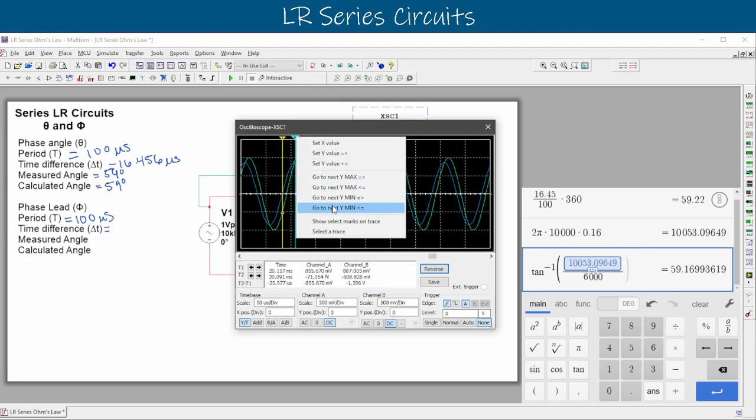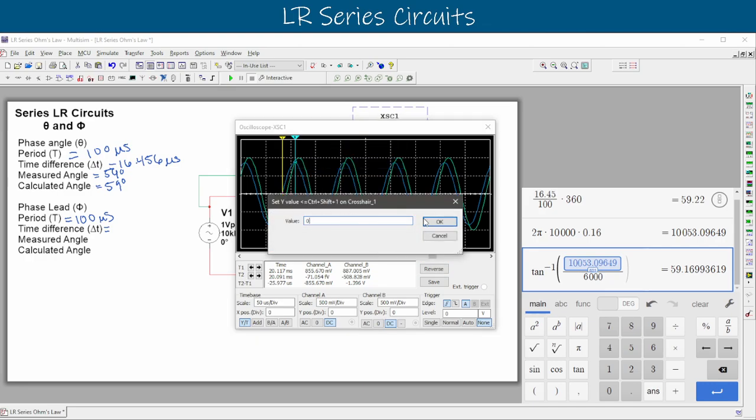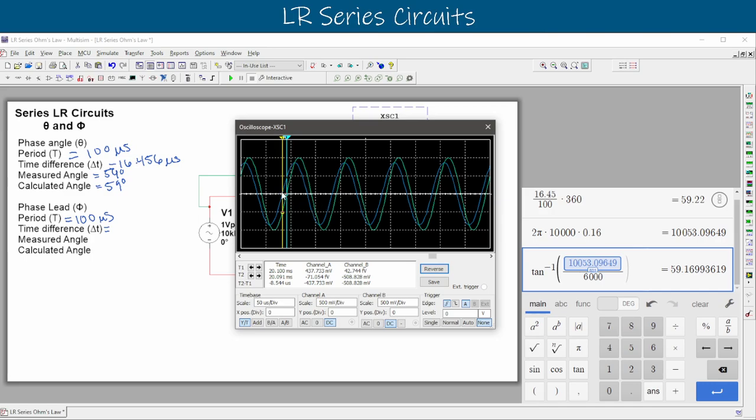And this actually shows something interesting with our time interval too. So we'll go backwards down to 0. And that's going to move us right back down. And we see that that's right next to each other. We do see a negative time interval, but that's just because I have the T1 on the other side of T2, right? And it kind of shows us what this phase angle means as well. It means that that inductor has pushed something backwards, right? The voltage across the inductor showed up before the actual source voltage. And that's what we're seeing there as well. So this is not a negative time value. Time cannot be negative. But this is 8.54 microseconds.